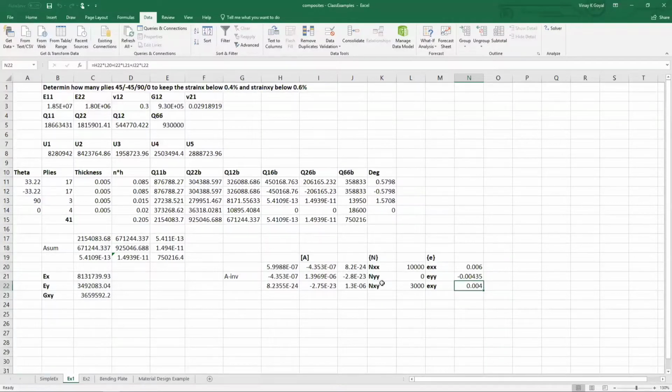Now you can use this also with bending moment. One thing you can do is turn bending moments into force resultants, and there are many ways to go about it. Similar to when you have a bar subject to axial loading, and a bar is also subject to bending, the outer fiber stresses are going to be Mc over I plus minus P over A. You can always come up with an axial load that encompasses even the bending loading conditions. Very similarly, you can tackle bending problems in the very same way.